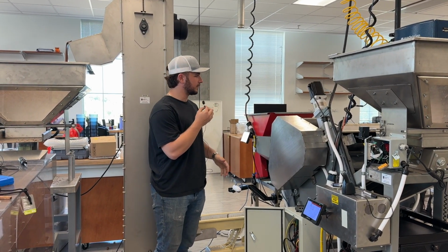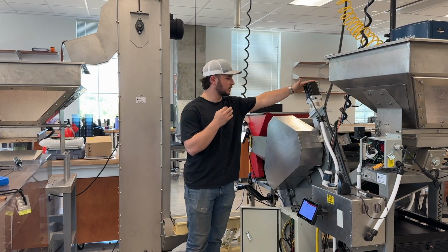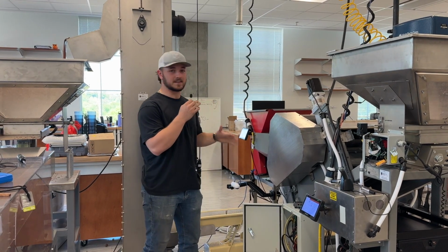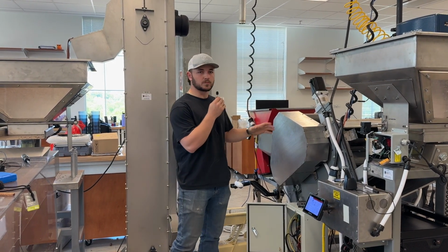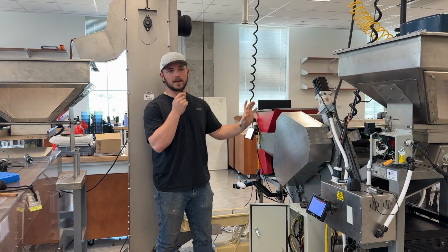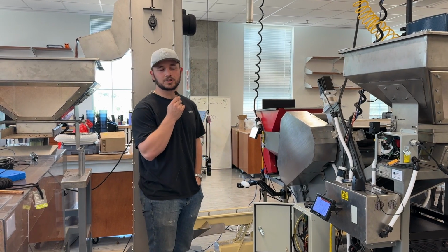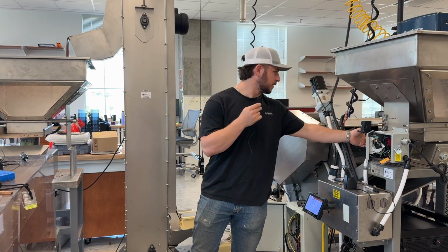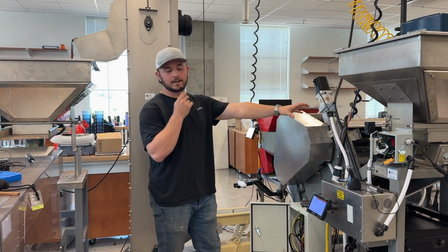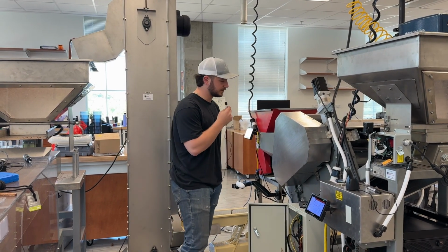Now we've implemented things such as here on the JC, we have a servo that can change the height of the plate that is impacting the pecans. With this, we can precisely change that relative height of the plate, giving us more precise control of the cracking dynamics within the machine. Also, as mentioned in a previous video, we have full control of the feed rate of this conveyor here using a computer vision model.